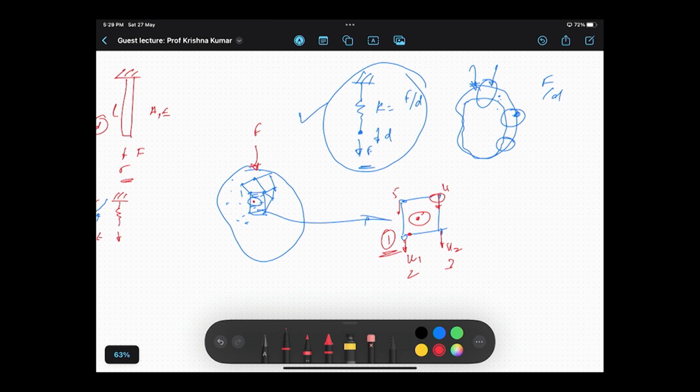This kind of behavior, where the position determines his allegiance, is called interpolation. So we are going to interpolate the displacements in terms of where he sits. If you choose a point right at the center, then his displacement would be the average of the displacements of the 4 blue guys. If the red guy sits exactly at the blue point, or very, very close to it, then his behavior is totally controlled by that point, and so on.